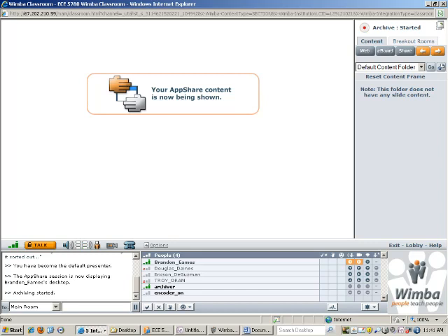Brad: On lab 3, when we're supposed to be displaying for our programming, we're doing it for really low frequencies. What are we supposed to be displaying for like 1.5 hertz? You're supposed to be displaying what the frequency is. For 1.5 hertz, are we supposed to put 1.5? Yeah, you should not be printing out integer values there. You should be printing out a floating point number.